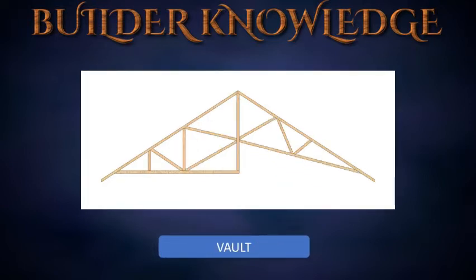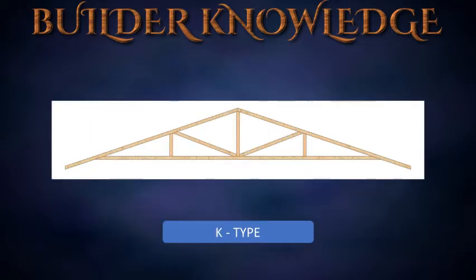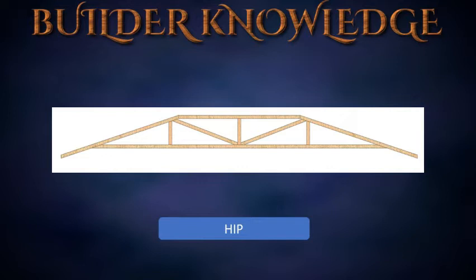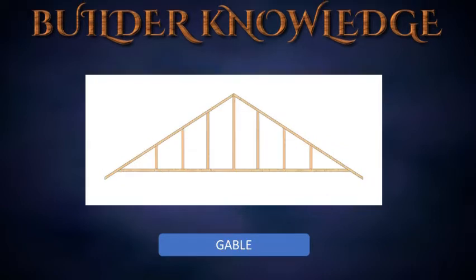Vault is used for vaulted ceilings. W-type is commonly used for gable roofs. K-type is commonly used for gable roofs with spans of 24 to 36 feet. Hip is a major truss in the Dutch hip system at sloping ends of a hip roof. Scissors is used for vaulted or cathedral ceilings. Gable is a non-structural member placed at gable ends to provide a nailing surface for sheathing.